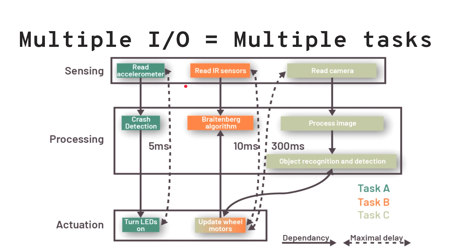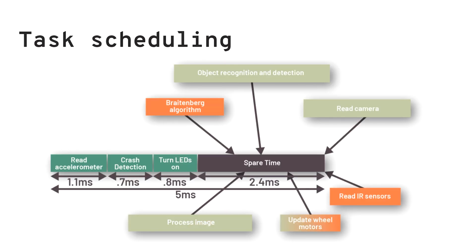The super loop was easy. Here, this is more tricky on how to actually schedule this. So you need to schedule in a way how you're actually going to do these X processes. Here, in the scheduling in the slide, you read the essential functions all the time, like the accelerometer crash detection and the LEDs, because remember, the one you have to sample faster than the rest will be the crash detection one with the accelerometer.